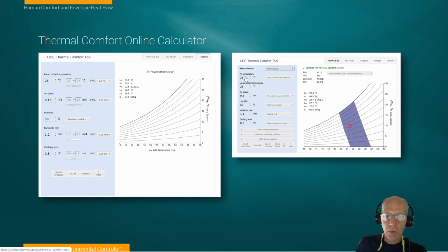So anyway, you have the input of the air temperature, the radiant temperatures of the surfaces, whether there's air moving, what the relative humidity is. And you'll notice some of these are actually describing the task. So in this case, we have typing, and it's 1.1 METs of energy expended. Clothing level, typical summer clothing, 0.5 clo is the imposed value for clothing. So this is a wonderful tool to develop this idea of thermal comfort in an environment.